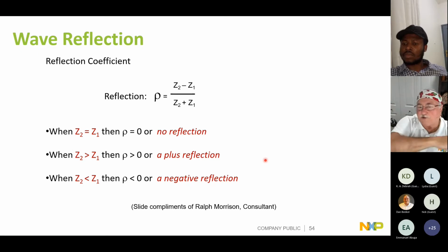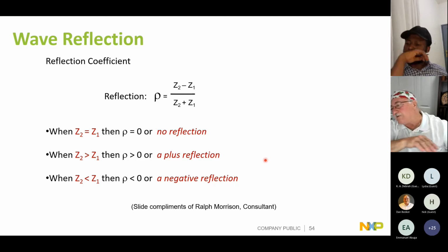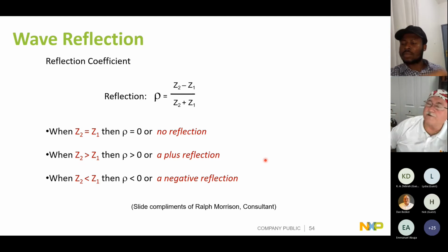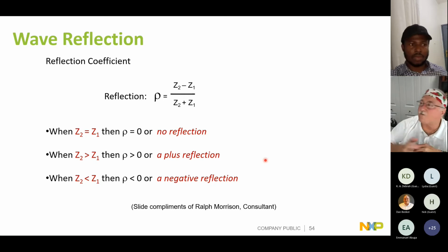And then it drops in voltage and causes a dip in the power. And then this now starts to source back to the receiver. And this goes back and forth until the energy is finally dissipated. It's either converted into heat, it's finally accepted by the receiver, or it radiates. Because again, every wavefront, you're translating some of that energy from E field to H field to E field to H field, and you're pushing these distortions or crosstalk across the circuit board. So this is why